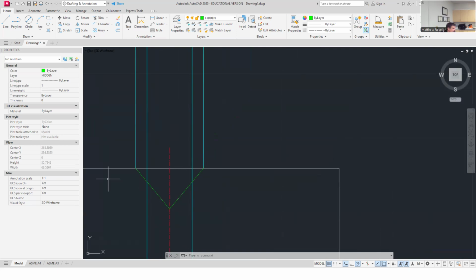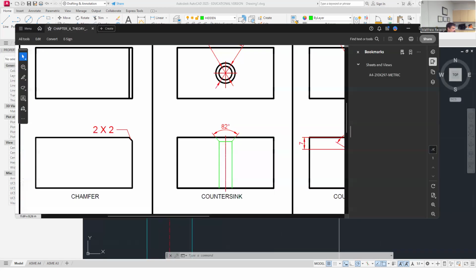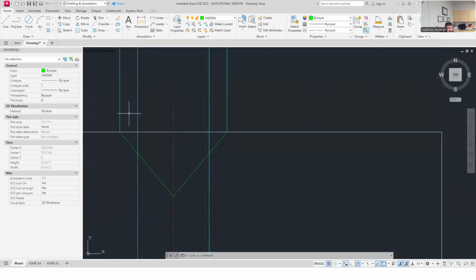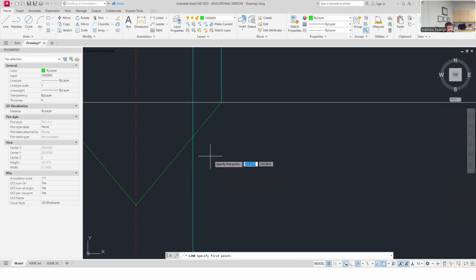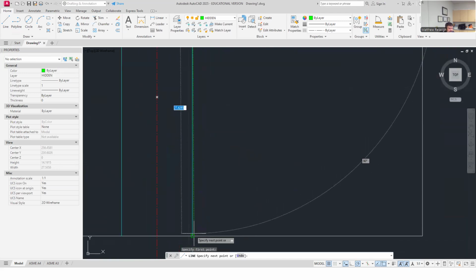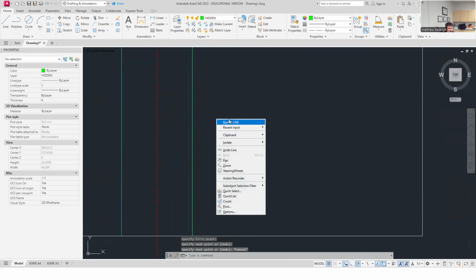And if I look at my drawing, the last thing I need to know is, from those points where they hit that side, I'm going to drag this down. The only part that's going to be mitered and beveled like that is just where it accepts the head of that fastener. So my hidden lines will now pick up from this point down through the block and to the end of the block like that.